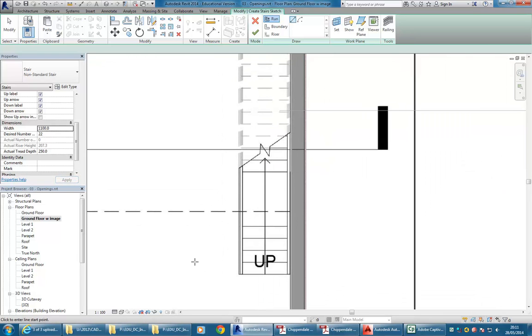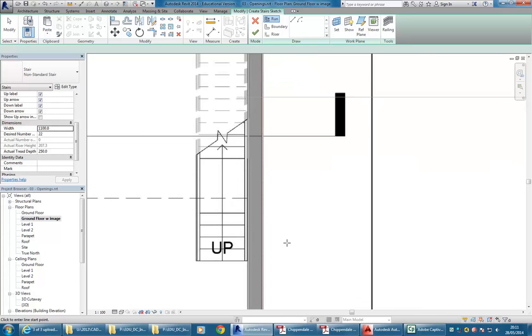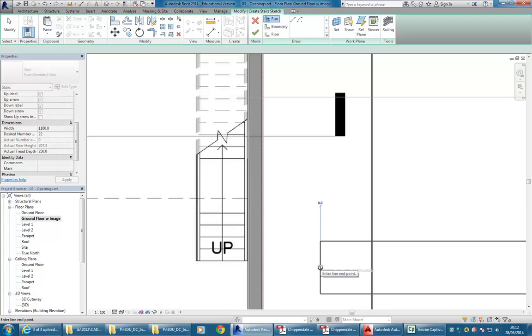Okay, so then just a few tricks when you go to draw your stairs. It's on the Run tool, so I'm just using Run with straight lines. And a good trick with stairs is to not try to make them in place. If you've set up all the lines, so if you've made the reference planes and established exactly where that stair should go, and I mean exactly, then do it there. But otherwise, it's actually easier to do it somewhere else, just adding space to the side. And that way you're going to avoid snapping to things that you don't want.